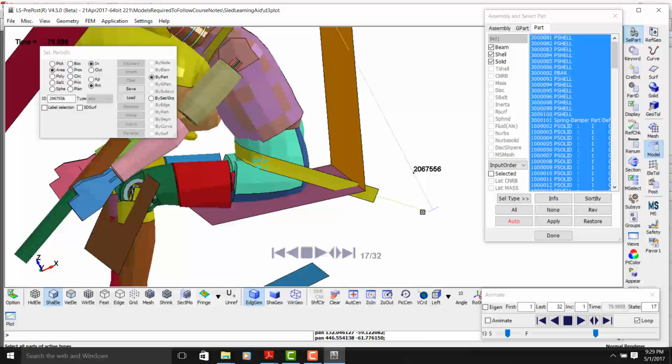And that spools in the material on this side, behaving like a retractor. And we give a very stiff retractor function because otherwise that retractor is going to spool back material out. But in the real pretensioner on the anchor side, it cannot spool out anything. It just pulls it in and keeps it there.